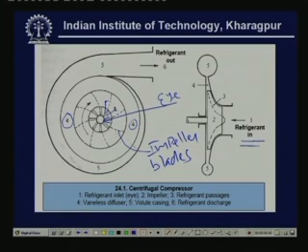You can see that the volute casing has a uniformly, gradually increasing area. So, as the refrigerant flows through the volute casing, its velocity reduces gradually and velocity is converted into static pressure. Finally the refrigerant comes out of the compressor at high pressure. Once again you can see how the refrigerant flow takes place through the different parts. As I said, part 1 is the refrigerant inlet and part 2 is the impeller. 3 is the refrigerant passages, 4 is the vaneless diffuser, 5 is the volute casing, and 6 is the refrigerant discharge.